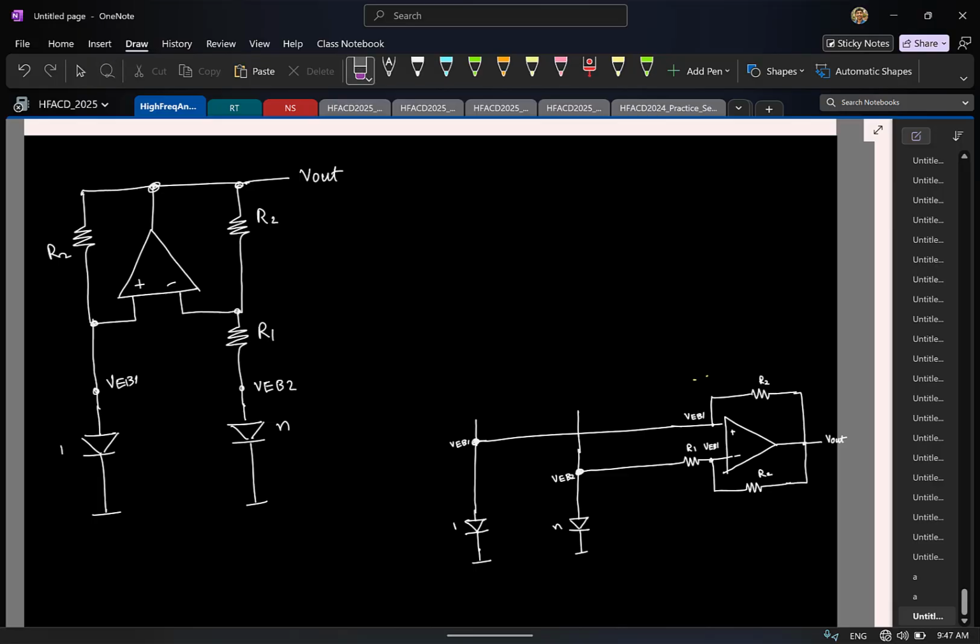Vout has not changed? Yeah, see, the entire calculation for Vout made the assumption that the diode drop is roughly 0.65 V, and that is guaranteed as long as sufficient current flows through the diode.